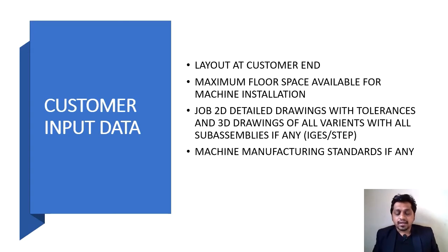And of course the job 2D detailed drawings with the tolerances, and 3D drawings of all the variants with all the sub assemblies, that is an important factor. We will see this in detail. And then the machine manufacturing standards, if any. Sometimes the customer has specific manufacturing standards that are required to be taken care of, so we should ask for that.